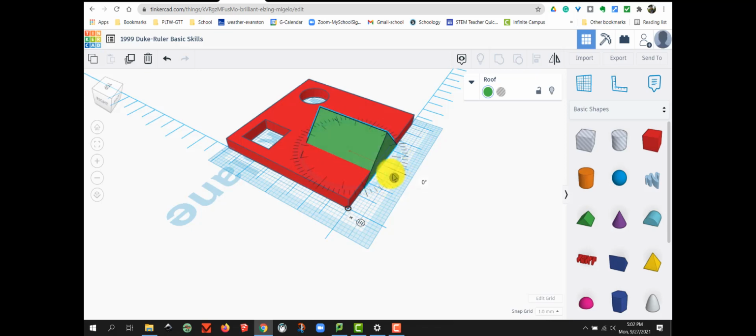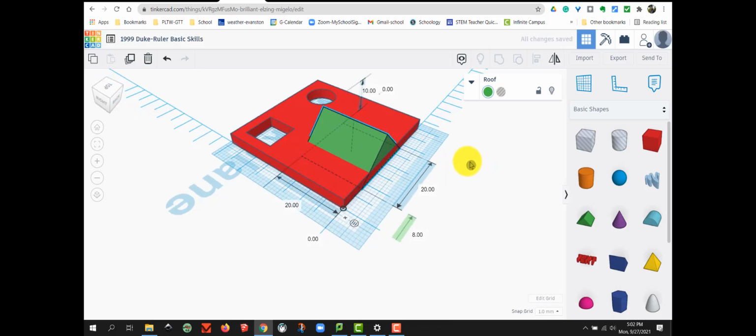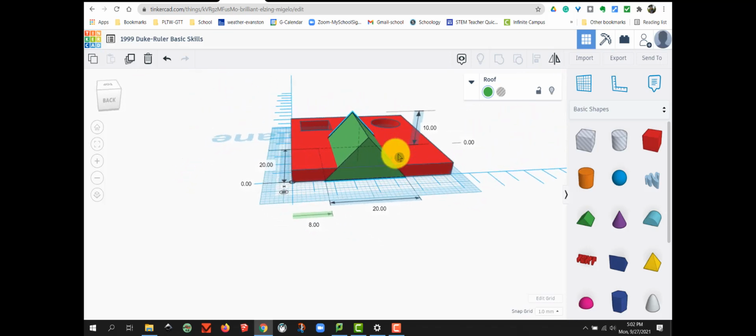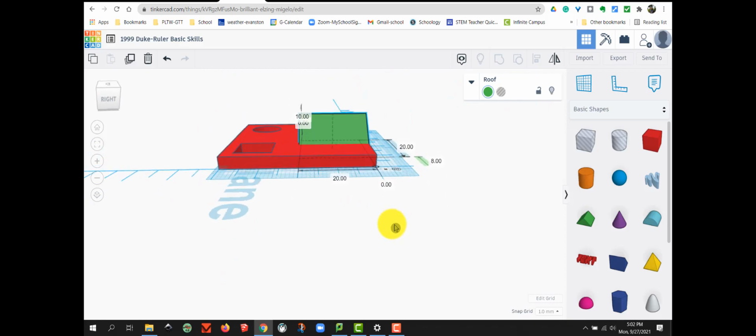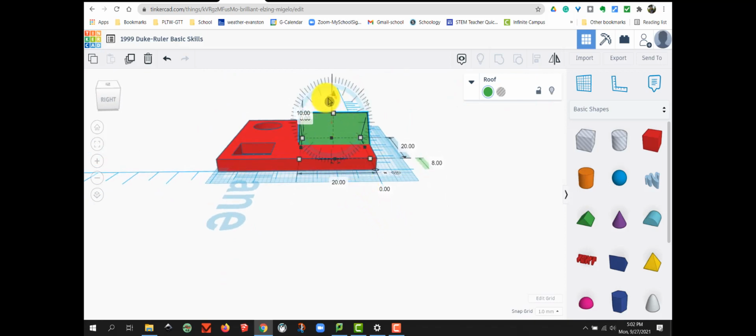Unfortunately, that compass is rotating the wrong way, so I have to find the other compass. If I rotate it just a little, maybe look at the triangle from the side, there is my other rotate option. When I hover over that, I'm rotating my triangle the other direction, still not the correct way. So instead of looking at it from this side, let's rotate our triangle this way. There's my third rotate option. Let's rotate it this direction so it's standing up.